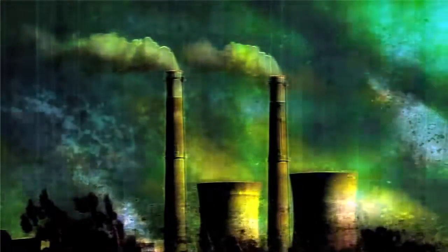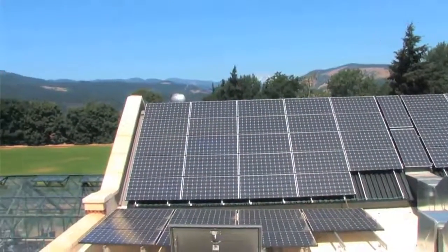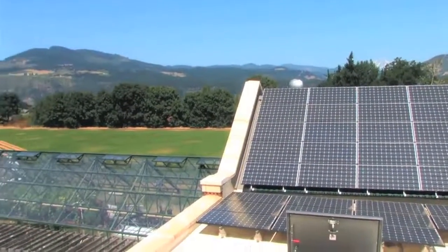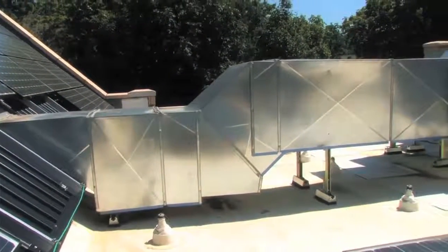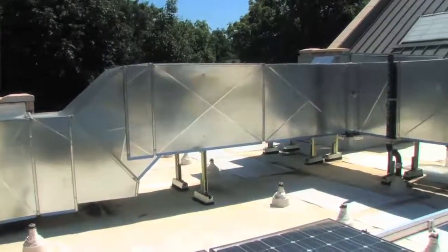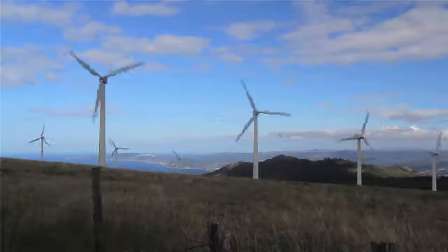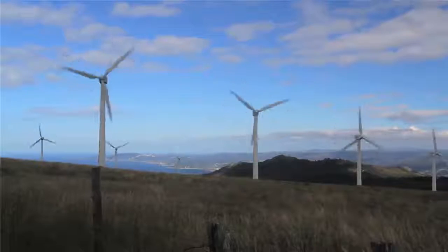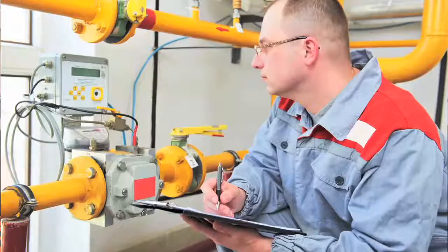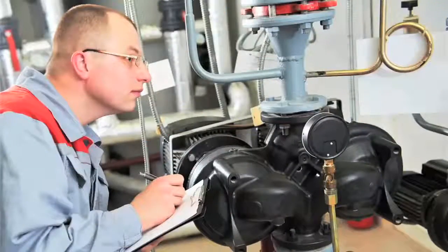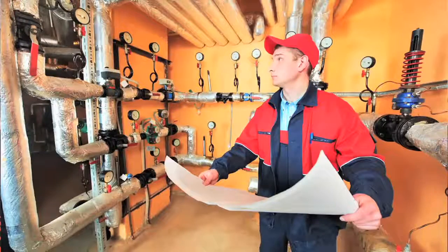Efforts to address energy through green building focus on two interconnected elements. First, we have reduction in the amount of energy required. This is done through integrated design and addresses orientation, building envelope, materials, systems, and other strategies. Secondly, we look at reducing the impacts from the energy that we do use. This is through renewable energy, as well as refrigerant management. Tied into both of these strategies is ongoing energy performance, or commissioning and verification, to ensure that buildings continue to operate as they were designed.